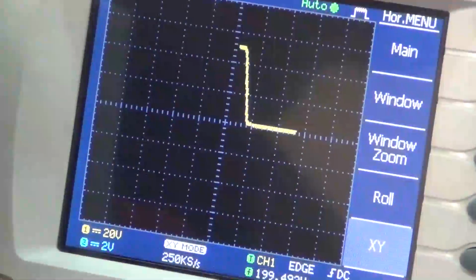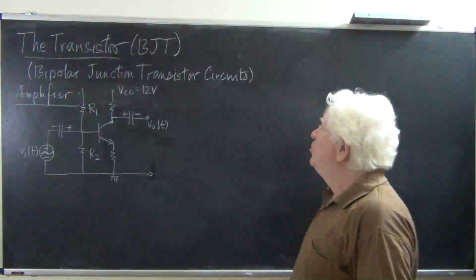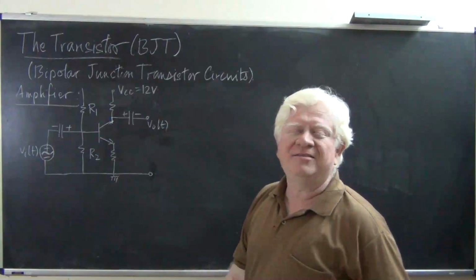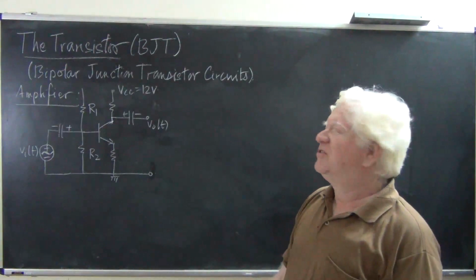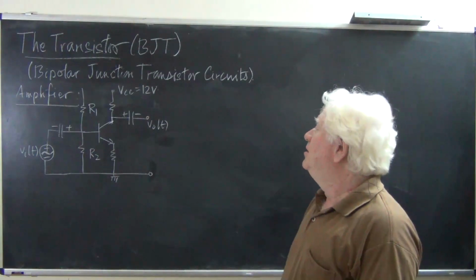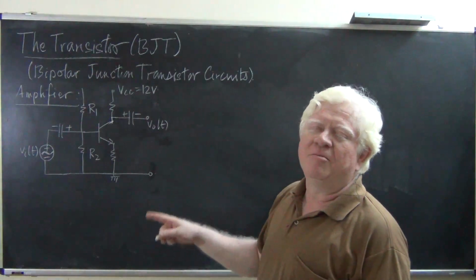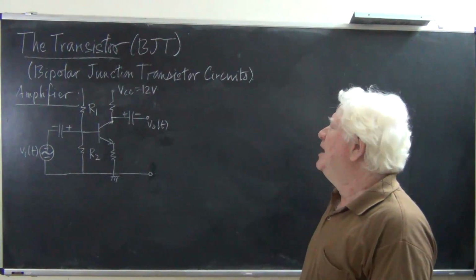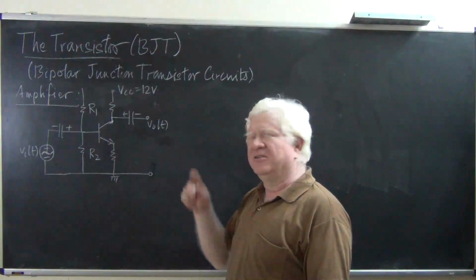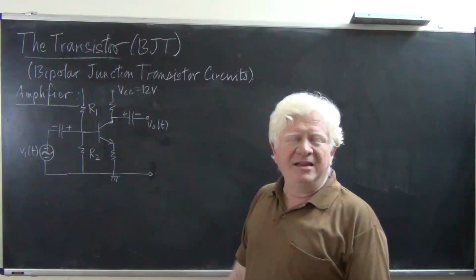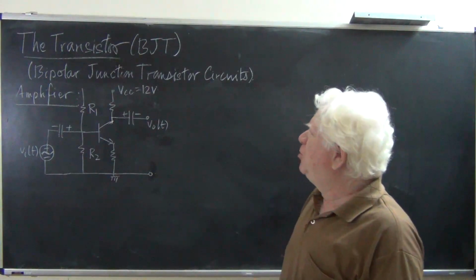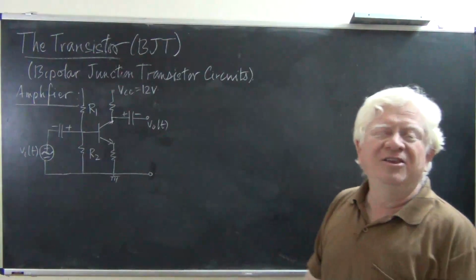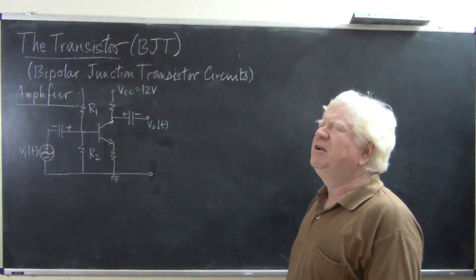So this is the amplifier circuit. The amplifier is supposed to act as a linear system and convert the input to an amplified or magnified version of itself. As you already know, it is inherent for the BJT common emitter circuit to have an inverting property. When the base voltage goes up, the collector voltage goes down, and vice versa. So while this will do an amplification, what it will produce will be some inverted amplification.